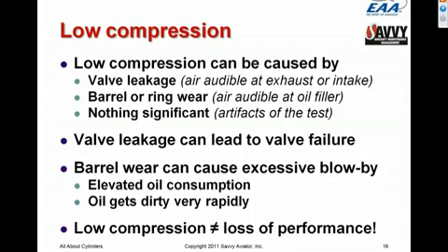One very common misconception I want to dispel before we go on to another subject is the notion that as the compression of a cylinder goes down, the amount of power that cylinder makes goes down. In fact, that is not true. Continental ran some very interesting tests back, I think it was in 2001 or 2002, where they took, I think, an IO-550 engine, put it on their dynamometer, ran it up to full power, and measured the power output. The engine is rated at 300 horsepower. Typically those engines put out more than rated power, and this particular one put out, I think, 305 or 310 horsepower.